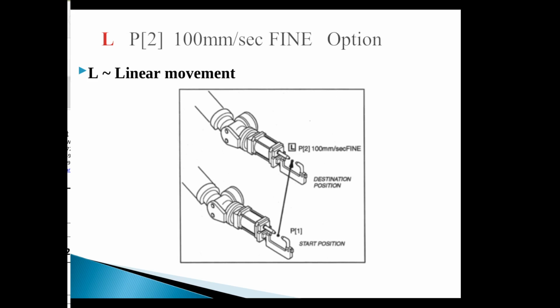Okay, so you always need to be very careful when testing, and you want to kind of test in teach mode, of course, and then test with the robot at low speed just to make sure everything's working, and then speed it up a little bit and then speed it up a little bit more until you reach full speed.